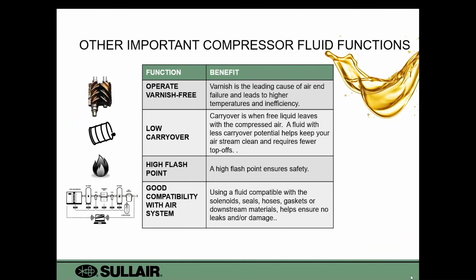You want to have a high flash point, a safe flash point, and most of the fluids out there have this. And you also want to have good compatibility with your air system. You want to make sure it's not too aggressive on your seals, your solenoids, your hoses, your gaskets, and causes any deterioration, which could lead to leaks.